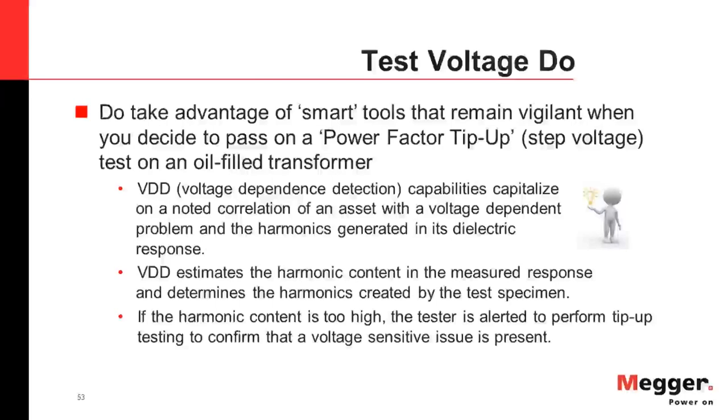And then lastly, don't bother with traditional power factor tests on a service-aged oil-filled transformer in the absence of its insulating fluids as a measure to assess moisture and the success of a dryout, even if you're reducing your test voltage to very, very small levels. Because as we've seen, power factor is relatively insensitive to moisture when it's at low levels.